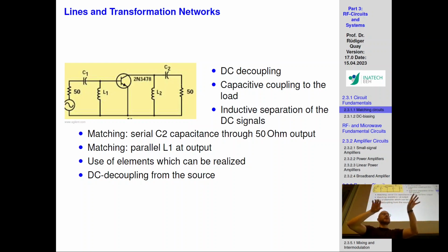If this device is not the same as this device, it gives you 5 dB, but maybe this device draws 200 milliampere at 4 volts, and this device draws 600 milliampere at 2.5 volts or something like that. So you have a different amount of current that has to be driven through the device, meaning that once you connect all of these to your power supply, there will be major fluctuations.